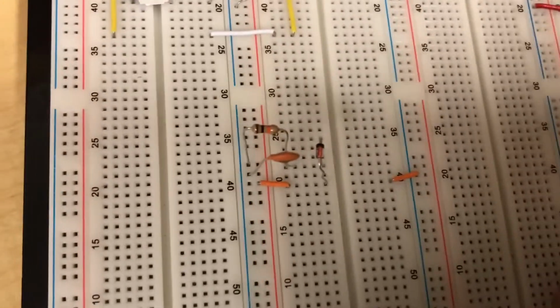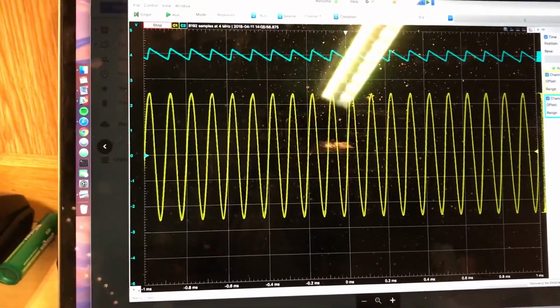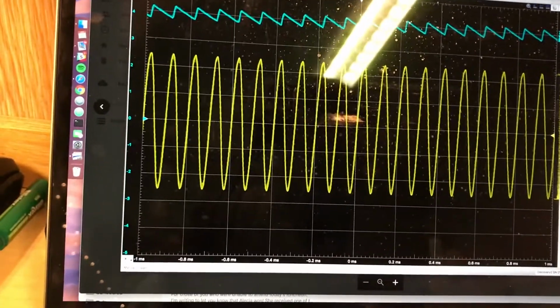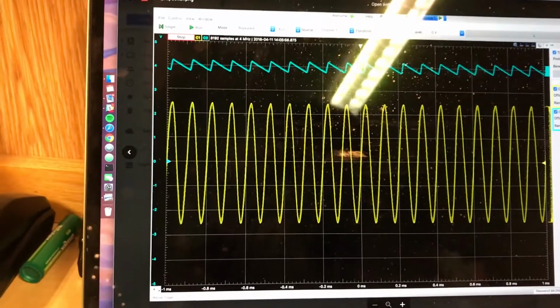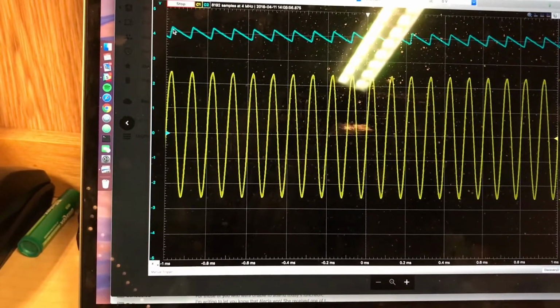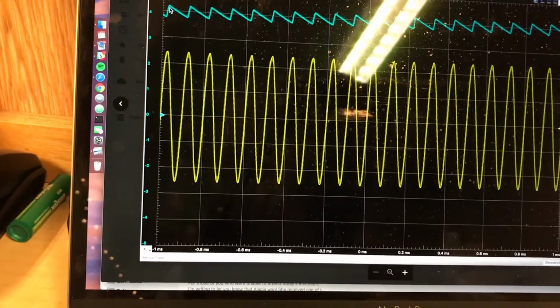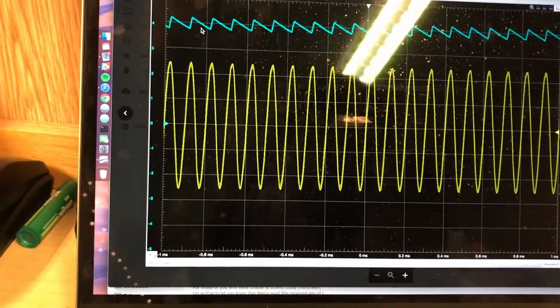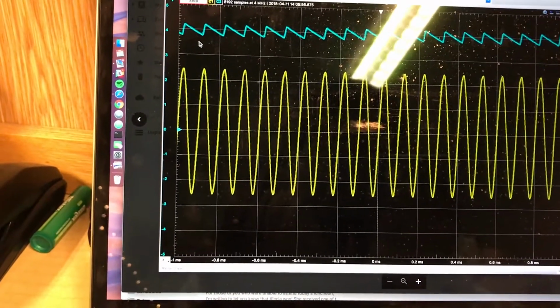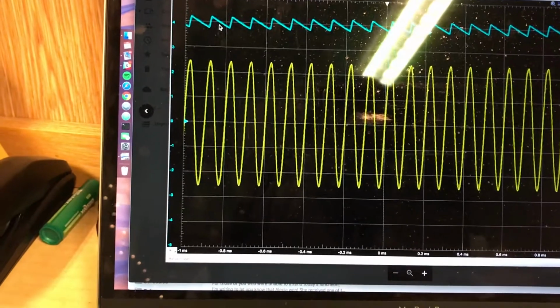And so what we see when we look at the waveforms for this is there is this, in blue you can see the voltage across the diode, and you can see that there is a ripple voltage, that the voltage will hover around this base voltage here, but it will dip up and below. So this is the way that we can turn this AC signal here into what's pretty much a DC signal.